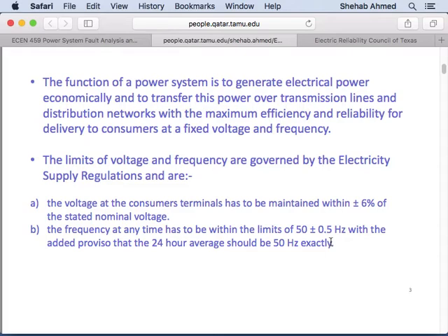And that's why you have a field winding control circuit. The field winding control circuit, what does it do? It controls the value of the magnetic field that's generated. So if you control the value of the magnetic field that's generated, then you can control the value of the voltage, right? So now you have control over the voltage and frequency. And that's how you control the generator, right?